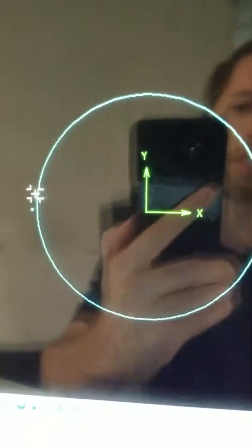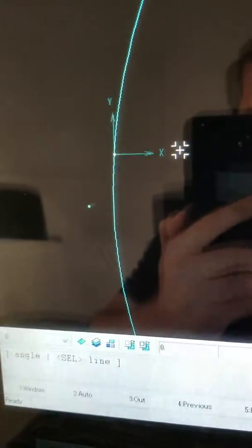But now we also need to give it, once we get to that tab cut area, where's our wire going to escape out to? So our relief point. So we have to make a point absolute from that point. Now there's a couple different ways to do this. I always cheat. I do auxiliary axis, and I just temporarily move my origin point, and we'll click on that point, and we'll hit enter.